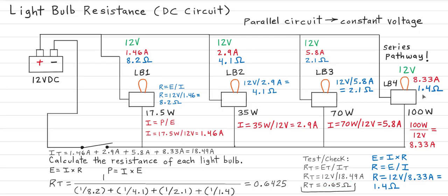1.8 something is wrong. And then you're like, what's going on here? Well, you have to treat the N return pathway as a series pathway with respect to circuit analysis. But when it's energized, then you can just treat all four as a parallel energetic relationship. So that's the little bit of a tricky part here, but you have to be careful. So if you start working with series parallel pathways, then you'll know this potential stumbling block. So treat the N circuit as if it is a series pathway when you do the circuit analysis.